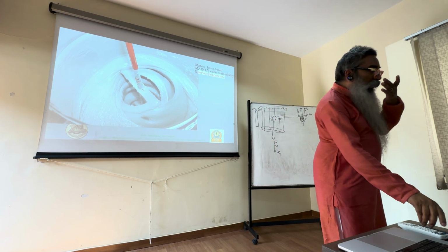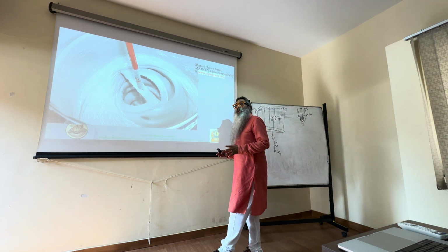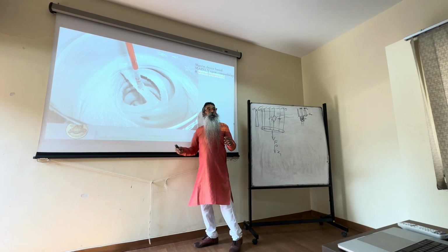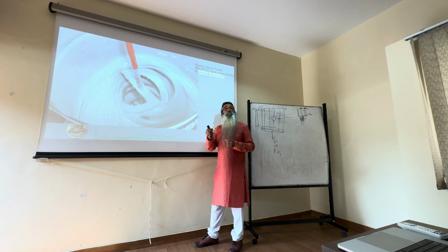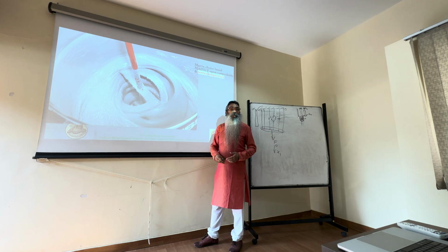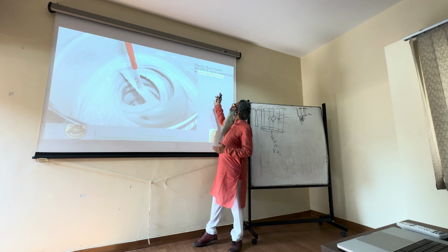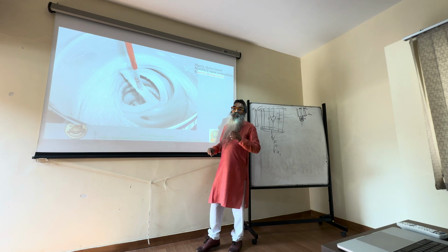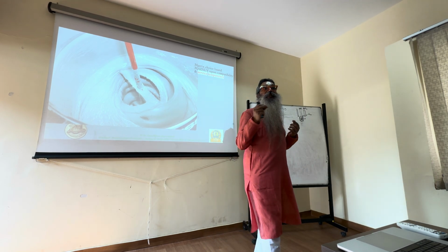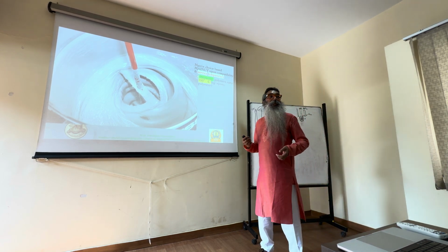But traditionally, and even today for a large part, once I have decided on the fiber, I have a bunch of matrices that can go with it. Then I will ask you what is the typical temperature range you expect for that component in service during its life, during various flight phases of takeoff, landing, climb, descent, cruise, maneuvers, etc. What is the maximum temperature it can reach? What is the minimum temperature it can reach? And based on that, I have to choose a matrix which can sustain that temperature range, and it's usually the maximum temperature which determines that.